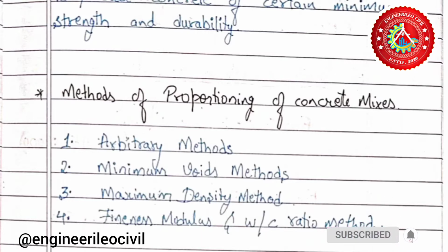The fine aggregates should fill the voids of coarse aggregates to give a dense concrete. The ratio of cement, sand, and coarse aggregates should be generally 1:n:2n, depending upon the strength required. The amount of water required is decided on the basis of workability, which in turn depends upon the type of work and compaction. There are different grades of concrete like M5 and M7.5.